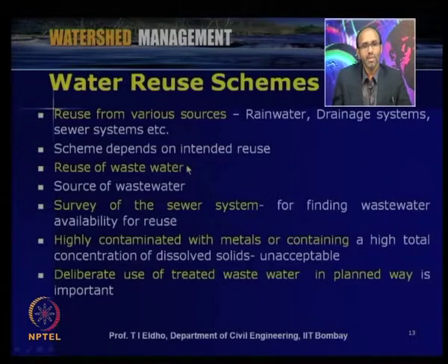When we are looking at the reuse of wastewater, we have to see the source of wastewater, whether it is coming from a domestic source or an industrial source, whether it is highly contaminated, or whether only some TDS or small kinds of pollution are there. So we have to do an appropriate survey of the sewer system for finding wastewater availability for reuse.